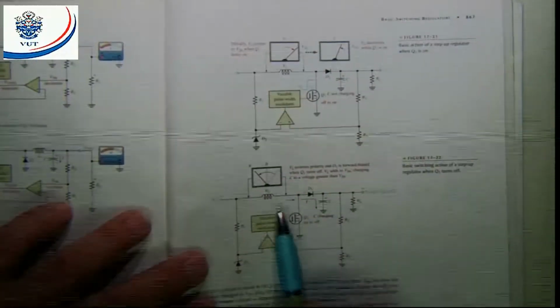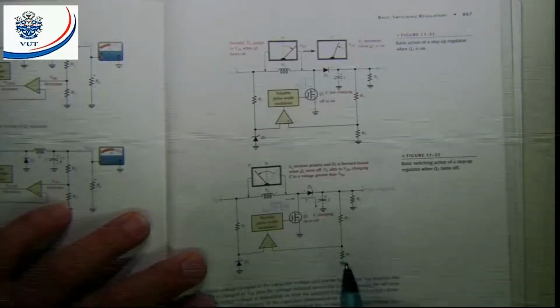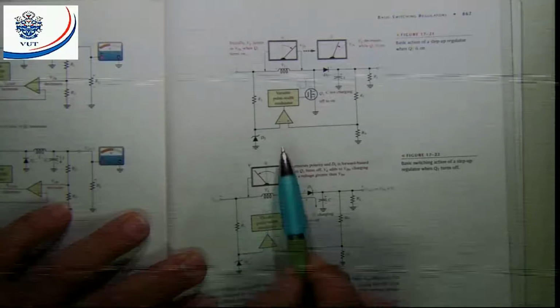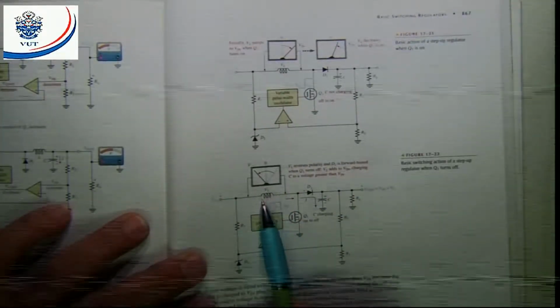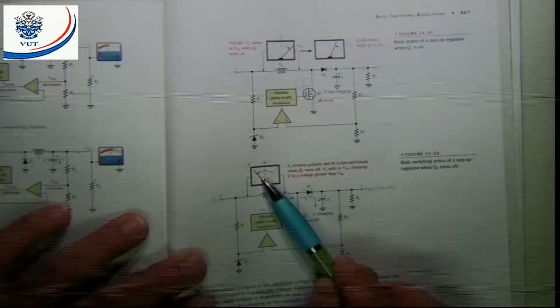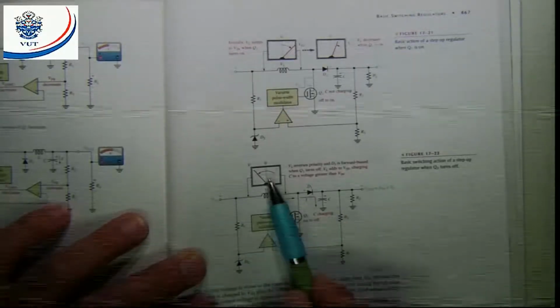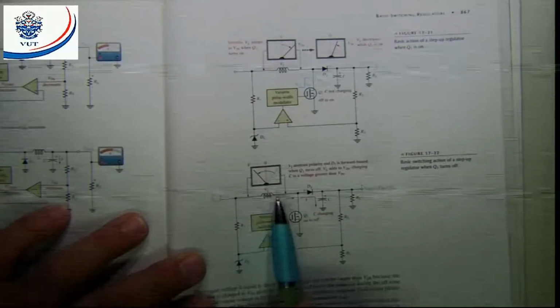Now, when my transistor goes from on to off, what will happen? The magnetic flux will collapse and it will generate an EMF with the opposite polarity. Now you'll notice the voltage will now be negative, positive, because the flux collapses and generates the EMF with the opposite polarity. Now it will be positive, negative, positive.